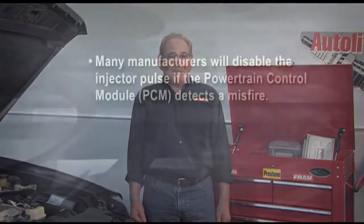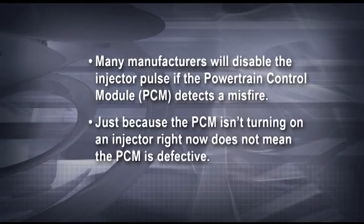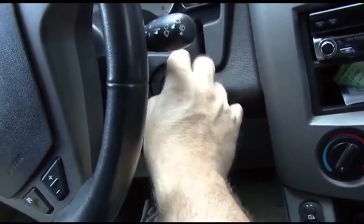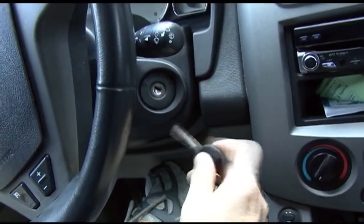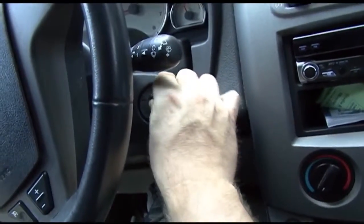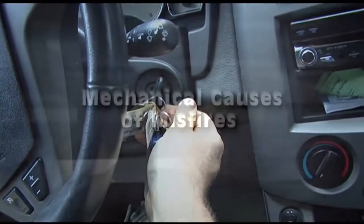Keep in mind that many manufacturers today will disable the injector pulse if the powertrain control module detects a misfire. Just because the PCM isn't turning on an injector right now, it does not mean the PCM is defective. Shutting the engine off and then restarting it may result in the powertrain control module firing the injector again until the PCM detects a misfire and turns it back off.